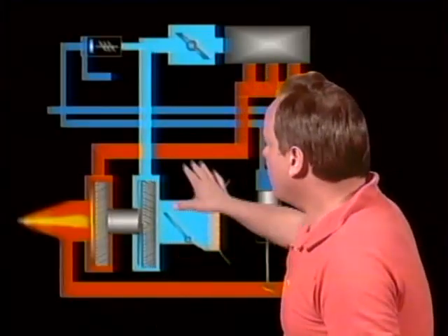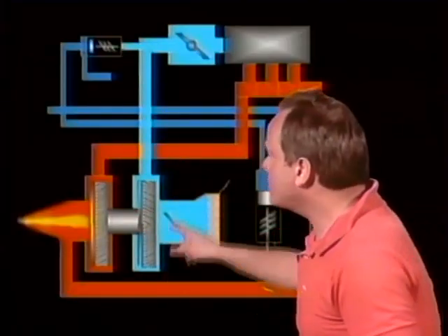They're the same thing. A supercharger is called an internally driven supercharger. So both turbochargers and superchargers, according to the FAA, are superchargers. If it's internally driven, it's what we call a supercharger, and it's driven by the engine itself. If it's externally driven, the FAA calls it a turbo supercharger or an externally driven supercharger, and it's what we call a turbocharger. And what drives an externally driven supercharger? The answer is exhaust gases driving a turbine are used to drive an externally driven supercharger.